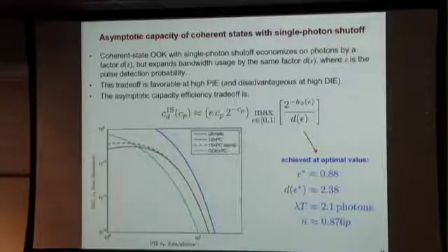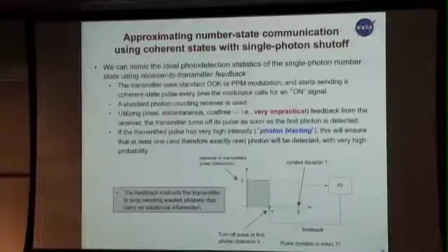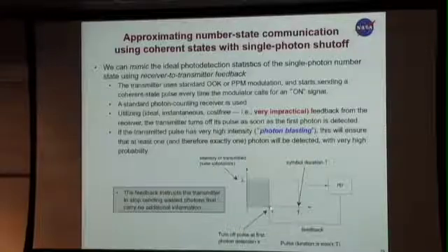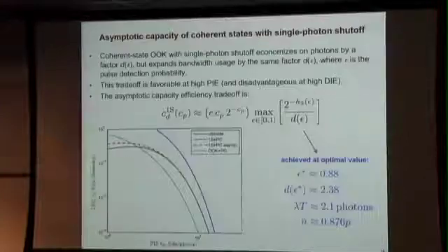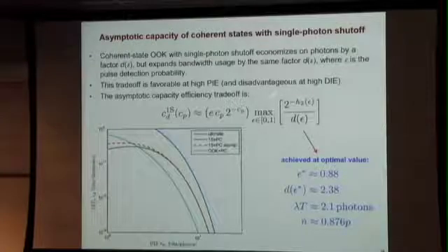What happens is there's a factor D by which you save photons, namely the average of the stopping time versus the full symbol interval if you were to transmit for the full symbol interval. But 1 over that is also effectively the amount by which you're increasing the bandwidth usage.